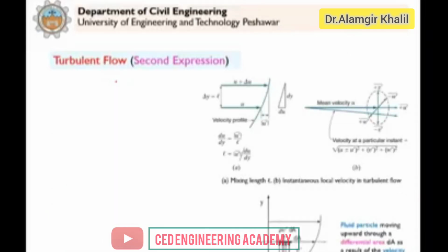Similarly, there is a second expression, and as I said, the second expression is based on the momentum principle. We apply the momentum principle in fluid mechanics and hydraulics in order to calculate forces in fluid flow. Whenever you want to calculate forces, we cannot apply the continuity equation, nor the Bernoulli equation, because the continuity equation is the law of conservation of mass, and the Bernoulli equation is based on the law of conservation of energy. So if we want to calculate forces in fluid flow, we have to apply the momentum equation.